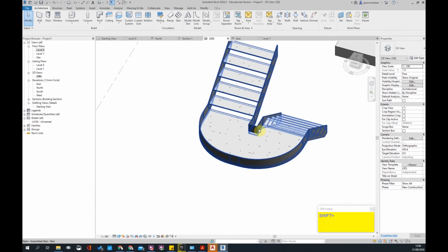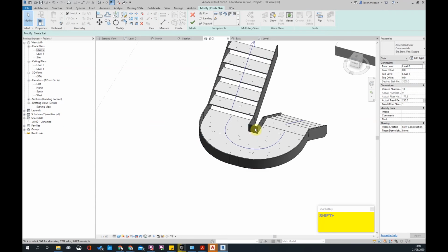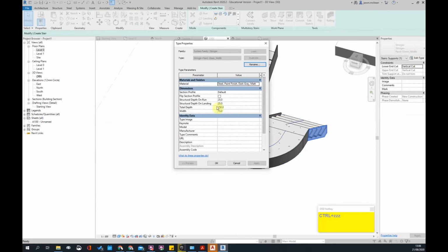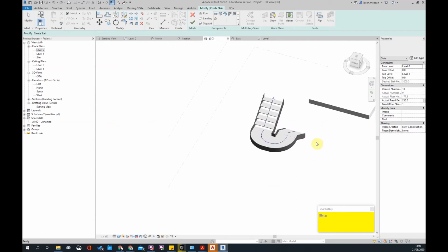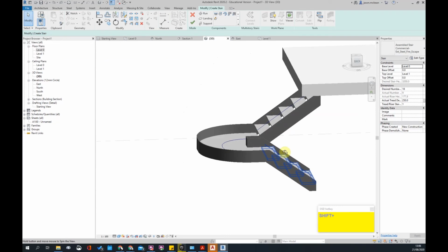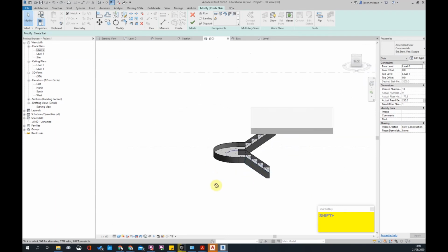Okay. All right, if you go and edit stairs, you can also get rid of these edges if you don't want to see them by selecting them, and you can add them back again. All right, and they're part of the stair, but you can always change the materials. You can change the width and depth of it, for example. But it's been pre-set up in your project to kind of work for what you guys are doing.